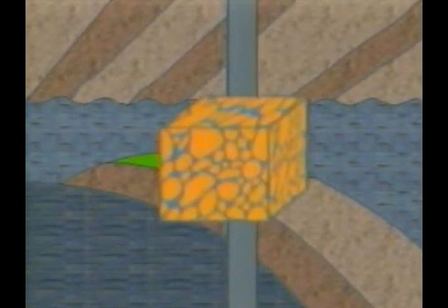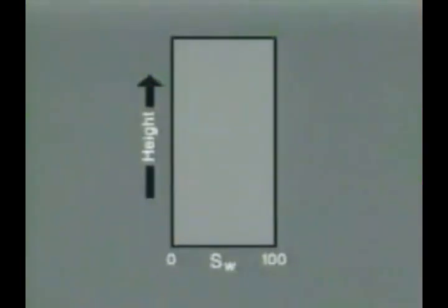The first factor that causes oil and water to mix takes effect when hydrocarbons migrate into a reservoir. The formation water is displaced, and the surface tension of water across the pore throats is too great for capillary forces to force the water out. This means that in water-wet reservoirs, there will always be a certain amount of formation water trapped and retained along rock surfaces. The saturation of this trapped water is known as the irreducible water saturation, S sub Wi.